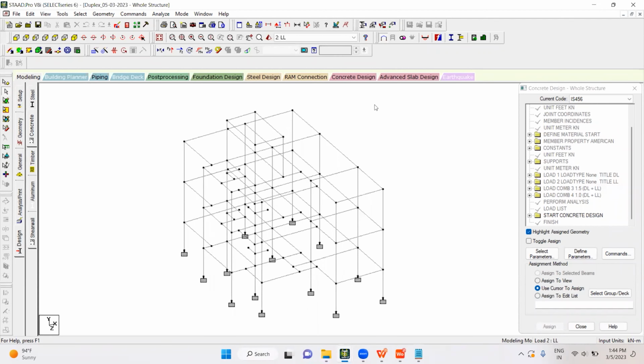So likewise, you have to analyze, design and standardize the more important elements, which need you to think every moment. Whenever you design a structure, you always have to think to fix the column sizes and the foundation sizes. Trust me, for slab and beam design, you don't need to think every time you design. You need to think majorly only to fix the column sizes, and you need to think more to fix the foundation size. That's all.